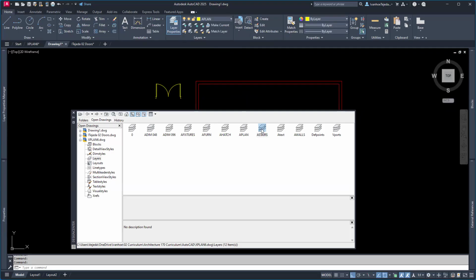Now watch this. I click on this layer, I right click it, and I say add layer, and it will bring a layer in to my drawing from another drawing file. This is what they called, I don't know if they still do, data mining. So you're borrowing data from one file, bringing it over to another. So that's how you can bring that in.